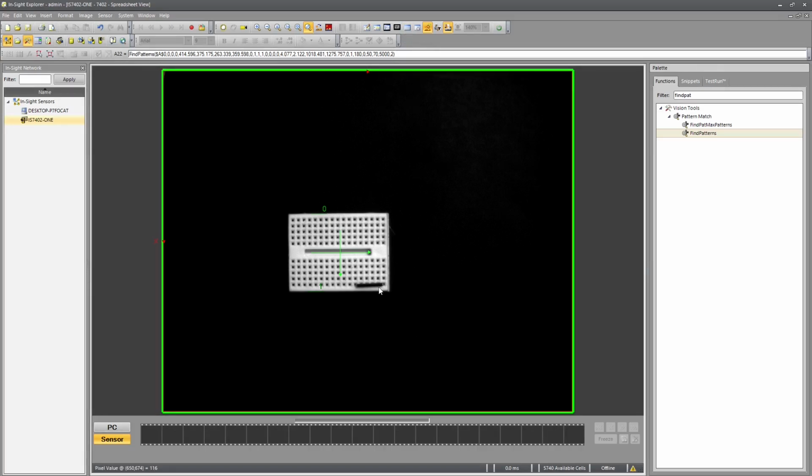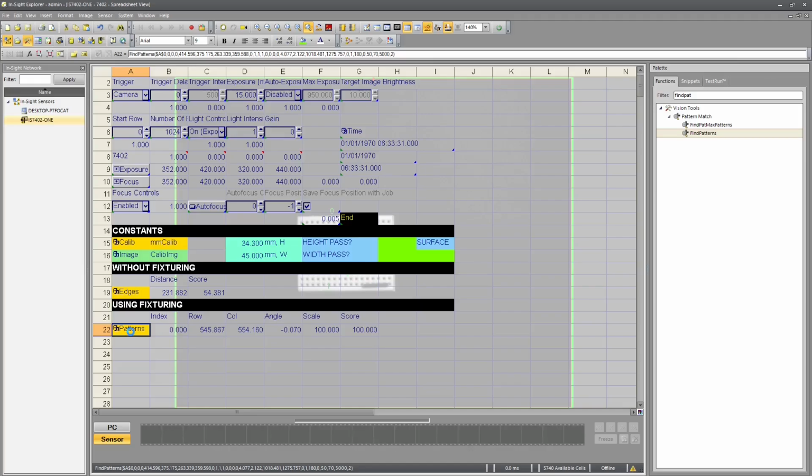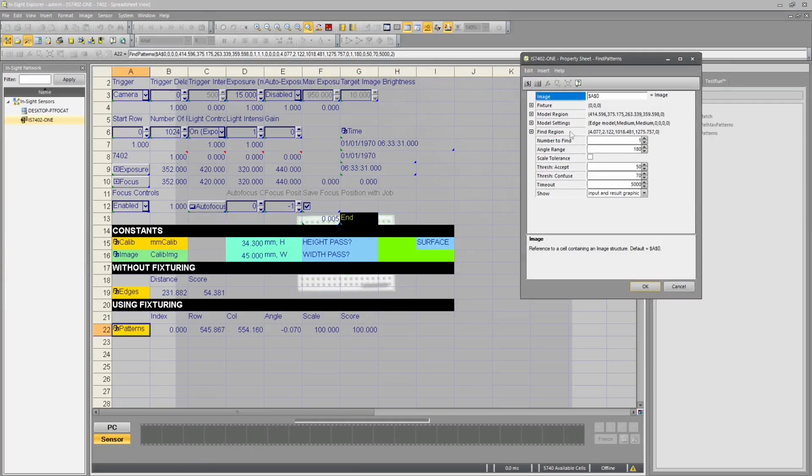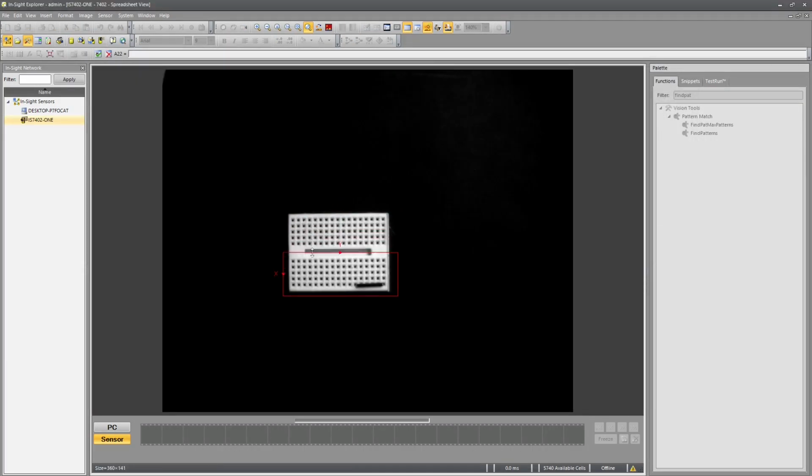So what we actually want to do is use the smallest area that we are most certain will always look the same, that is also uniquely oriented. To do this, we could change our model area to just be this bottom slice, since we're fairly certain that most of the surface is not going to be affected, and this has a unique orientation given that we have 3 edges and a demarcation on one internal part.